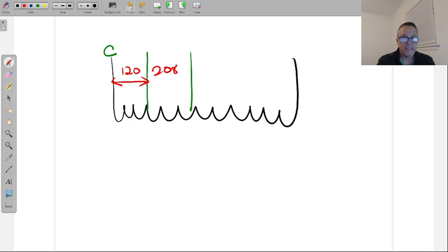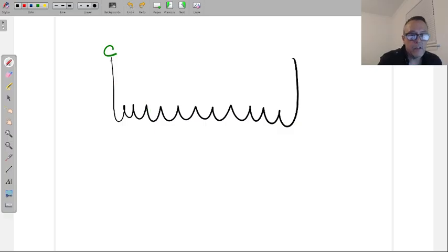If I'm going to connect this primary side to 480, then I need the use of the full winding because it's the highest voltage. And one of the things that our windings have to have is long distances between point A and point B when the voltages get very high. So it's just one winding that you can multi-tap into.